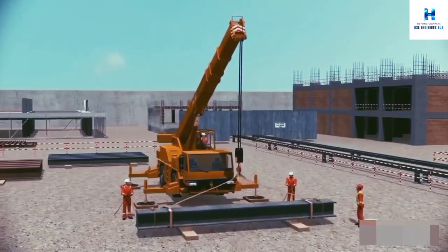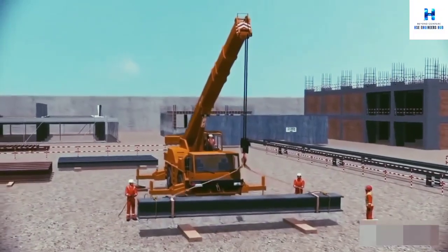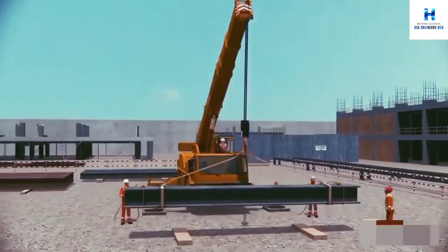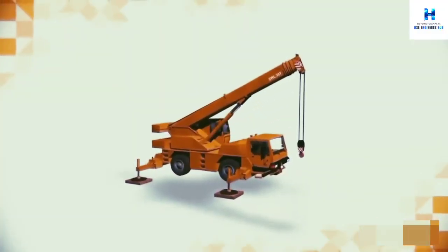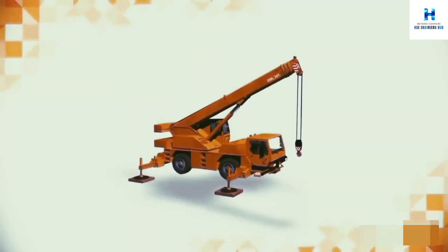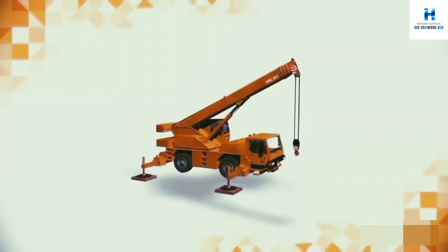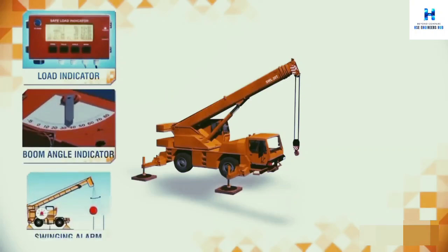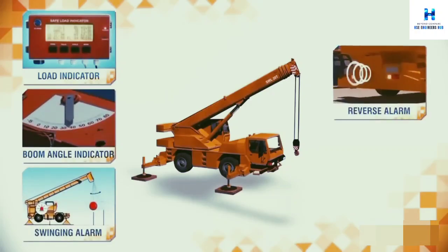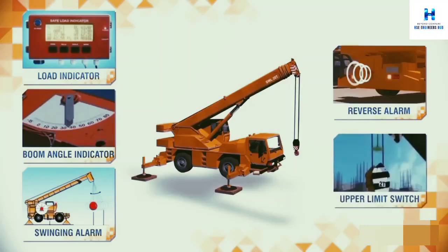ignoring the safety instruction provided by the manufacturer for using a machine, not following the guidelines of maintaining the equipment according to the manufacturer's instructions. For example, not checking load indicator, boom angle indicator, swinging alarm, reverse alarm, upper limit switch, etc.